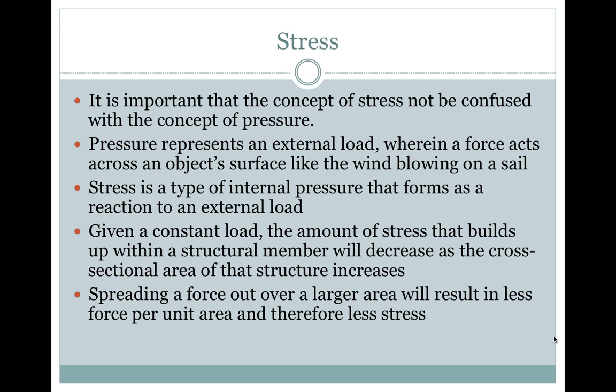It is important that the concept of stress not be confused with the concept of pressure. Pressure represents an external load, wherein a force acts across an object's surface like the wind blowing on a sail. Stress is a type of internal pressure that forms as a reaction to an external load. Given a constant load, the amount of stress that builds up within a structural member will decrease as the cross-sectional area of that structure increases. Spreading a force out over a larger area will result in less force per unit area and therefore less stress.